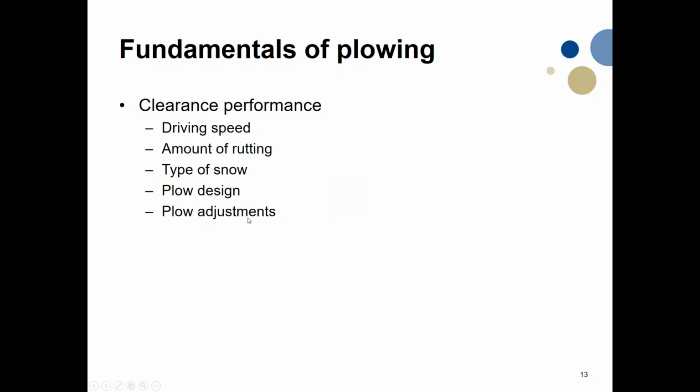And finally, the plow adjustments. How aligned is the plow? How are the cutter edges? Are they worn down? Are they still straight? For plows with a load relief system, how much downforce is actually on the plow? All those details can affect the clearing performance.